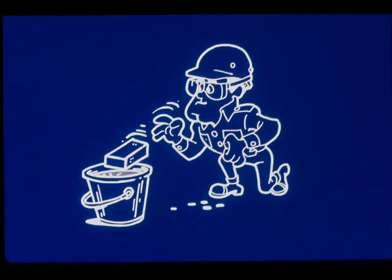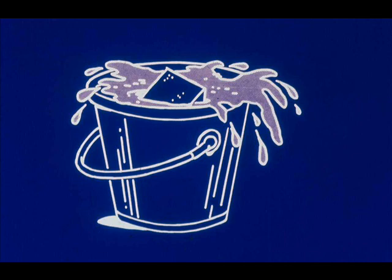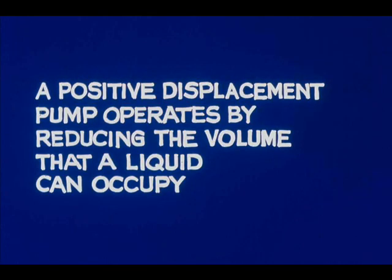This bucket is full of water. The water occupies the entire volume of the bucket. Suppose we drop in this brick. The brick reduces the volume the water can occupy, and some of it overflows. Our brick and bucket are a positive displacement pump. Not very useful, of course, but they illustrate that a positive displacement pump operates by reducing the volume that a liquid can occupy.